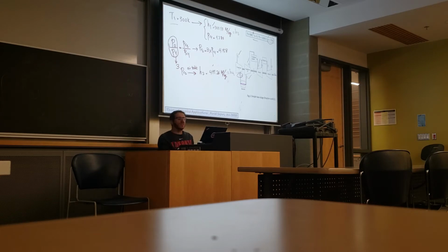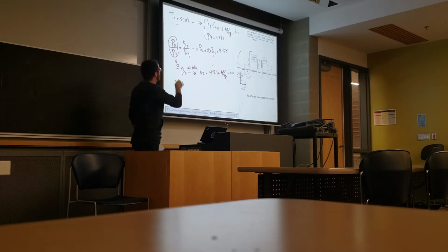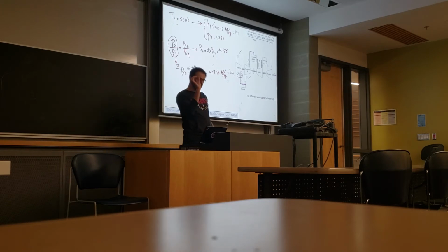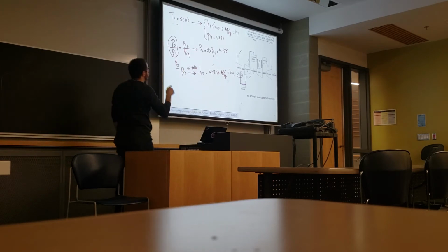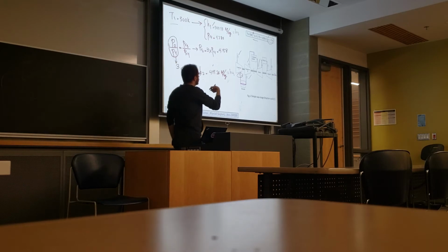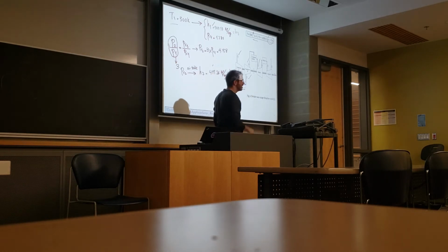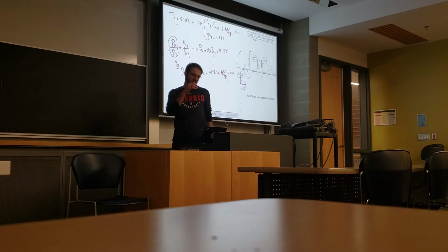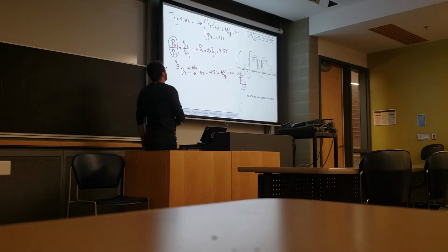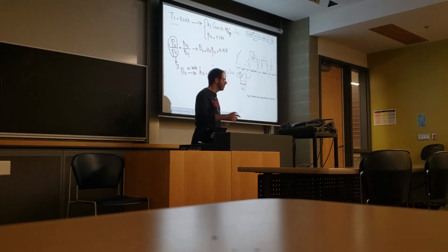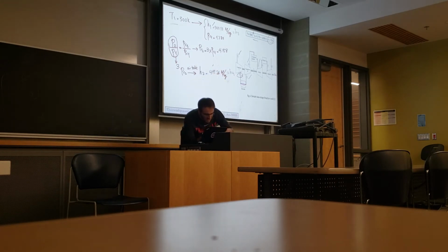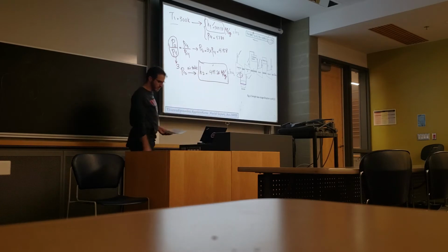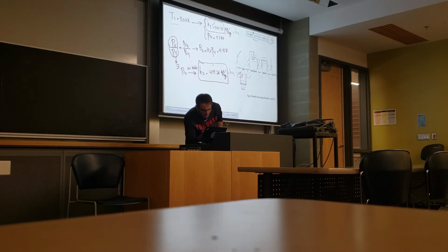One important thing in these cycles is that we go step by step to find H. H's are the key to find the work of compressors, the thermal efficiency, and all those things, because H comes into the energy balance equation, and from the energy balance equation we can find the work, the heat, and also the thermal efficiency for the whole cycle. So in your exam, in your assignments, just draw a line around it and put it in a box, to make it easier for us.